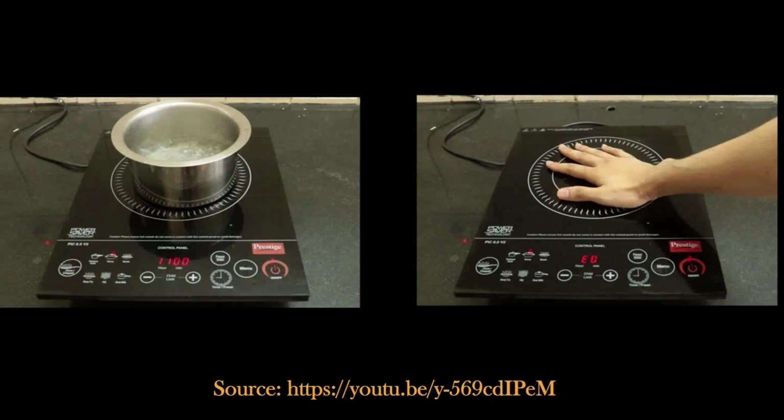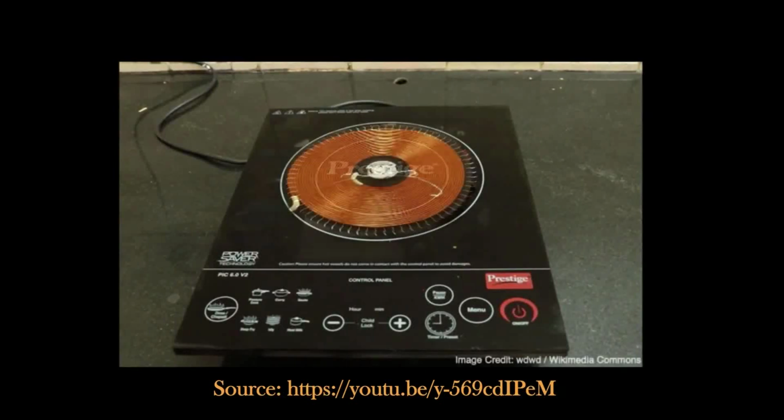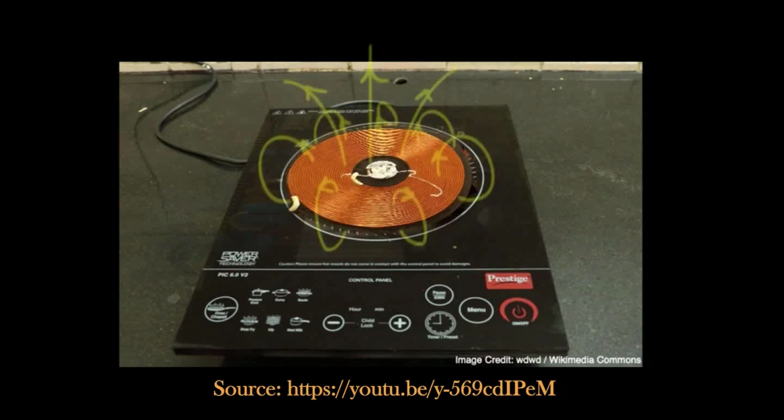So what are these eddy currents? To answer that question, let's look inside the induction cooker. If you could open it up, you might see a lot of things, but the most important one is a coil at the center. And we know that when you pass current through a coil, it produces a magnetic field. When you turn on the switch, a current starts passing through the coil and generating magnetic fields. But what's important is that the current is fluctuating. It's changing its direction continuously. It's called alternating current, and it changes its strength. As a result, the magnetic field that it generates also keeps fluctuating in direction and in strength.